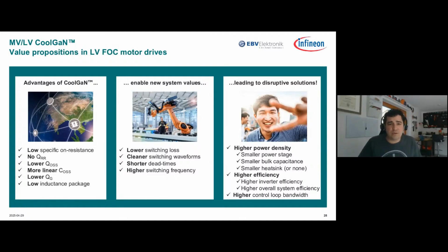You can also reduce your dead time to almost zero. We're talking about going from 1 microsecond to 50 nanoseconds, or going from 300 nanoseconds to 10 nanoseconds. So it's really improving your THD, your voltage utilization in terms of maximum speed. Now, all of these things are true if we don't change the frequency.